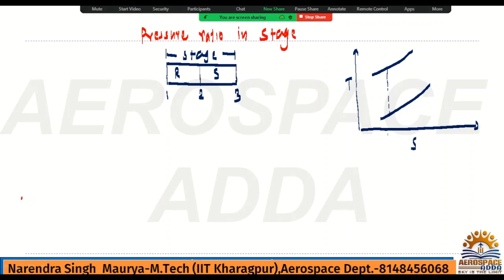This is the ideal straight line because entropy is constant, and this is the actual line, because this is the compressor, so pressure is rising. First point is 1 and this is 3, okay, and I'm talking about the total values, so this is 03 and this is 03 dash. Why 03 dash? Because it's the ideal or isentropic. And 1 to 3 is the actual rise.